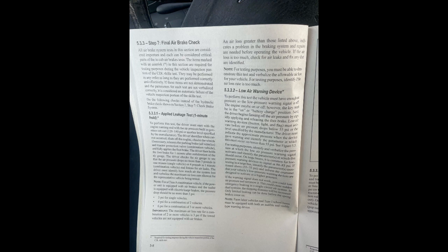The driver then holds the foot brake for 1 minute after stabilization of the air gauge. The driver checks the air gauge to see that the air pressure drops no more than 3 pounds in 1 minute, single vehicle, or 4 pounds in 1 minute, combination vehicle, and listens for air leaks. The driver must identify how much air the system lost and verbalize the maximum air loss rate allowed for the